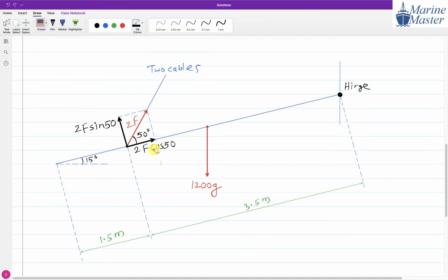But if you take components, initially you may feel, oh sir, taking components is very difficult. But once you understand how to take components, then moment calculation and all other calculations become very easy. Our first task in mechanics is to become expert in taking components. And remember, it is not always that one component is horizontal and another vertical. According to the situation, we will take components.